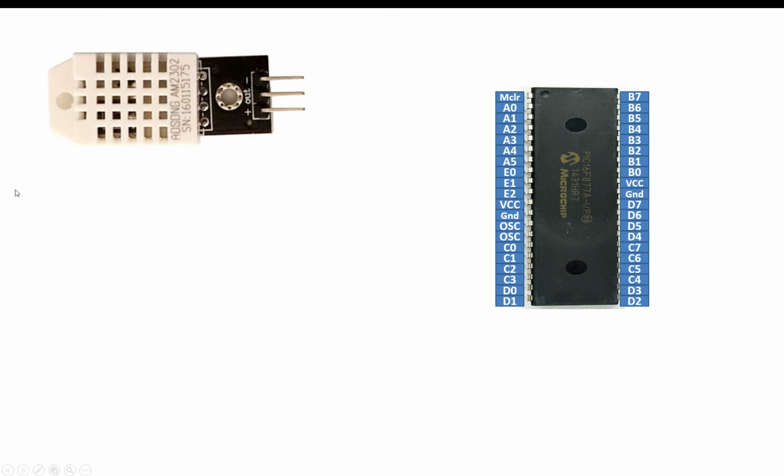It is just like the DHT11 sensor, but the difference is it has a bit of a different command structure to fetch the data. It is mostly the same, but it has more bytes. Like you have to fetch the data in 2 bytes rather than 1 byte. Now guys, the other thing is it is more accurate. It is a better version of the DHT11. So I will make a video on the difference between DHT11 and 22 soon. So let's right now do the connections.